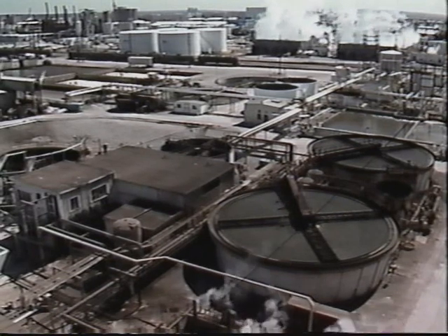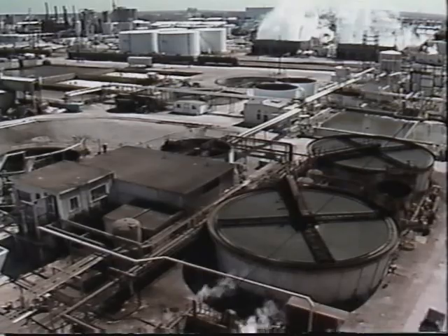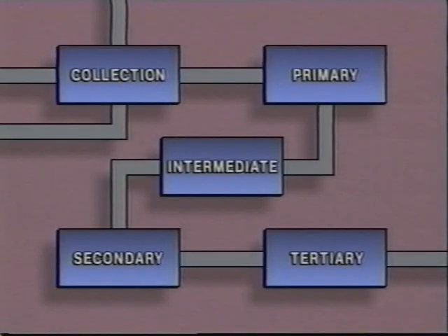The first example involves a wastewater treatment system, a system that's used in many industrial facilities. Before we investigate a particular troubleshooting problem, however, we need to describe in general terms how the system works. We've divided this particular system into 5 major sections. The wastewater first enters the system through a collection section. This section typically includes a sewer that routes the wastewater to the rest of the treatment system.